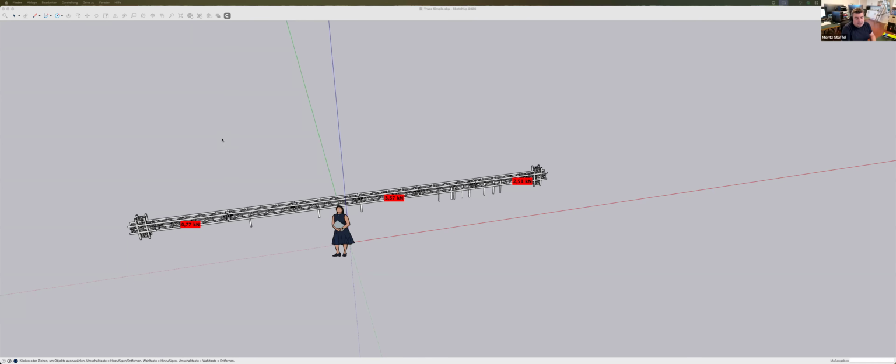We have added the friction calculation to Production Assist in a nonlinear way, so that when the friction is exceeded, you can tell Production Assist that the support should also fail. We have a new way of calculating the complete system. It's called delta P, or second order calculation. That is something that applies basically to all the calculations. It's a nonlinear calculation approach.